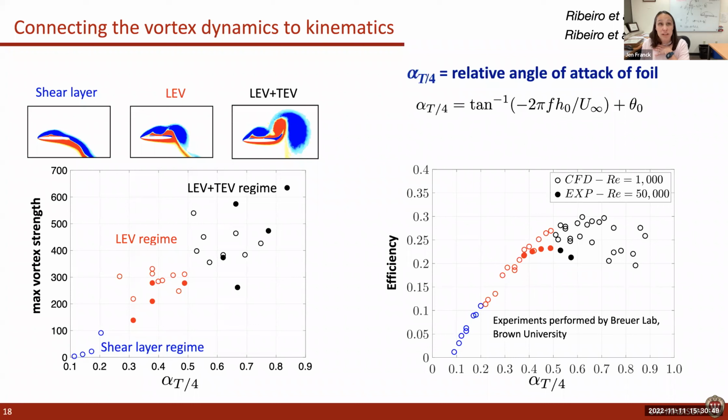Except the swept area is going to change each time you change your heave amplitude or angle of attack. So that denominator depends on your stroke. Okay, so it's not just the lift force that's changing a lot, it's also the swept area. Right, so you're changing the numerator and denominator each time. Okay.